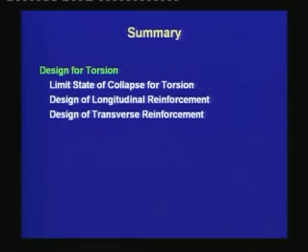Now, these expressions of equivalent bending moment have been developed based on the skew bending theory, and the expressions are used to design the longitudinal reinforcement. We had moved into the design of longitudinal reinforcement based on these expressions of the equivalent moment, and what we have found is that the general design principle for flexure is applicable for a member under flexure and torsion. The difference is that we are now considering equivalent bending moments instead of just the flexural moment. We have to satisfy the development length requirements as per the flexural design.